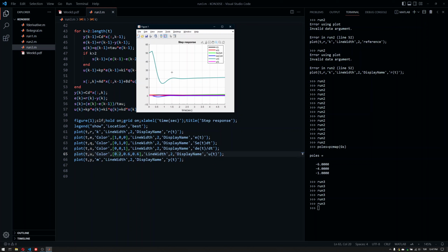Now, of course, the aim of this is not really the PID controller or the optimality of it, because that's going to be the next step here. But you can see that I have different information about the error here. We have the derivative, kind of. We have the integral. We have the error itself. We're combining them linearly with some coefficients, which we call PID coefficients, and then we end up in a control signal. Then I can use the difference equations and the zero-order hold method in order to simulate this.